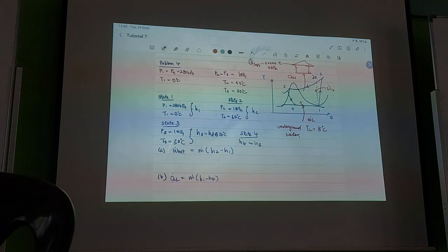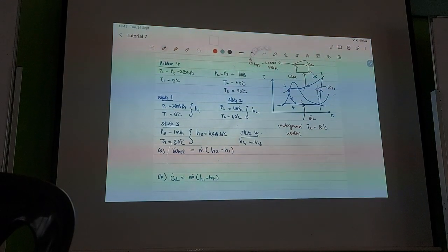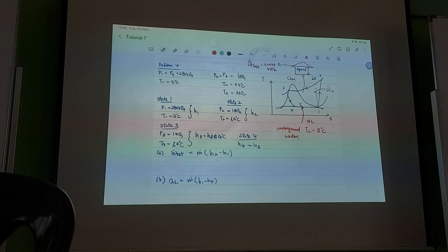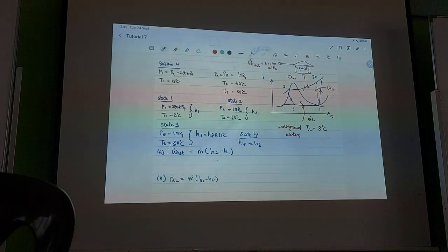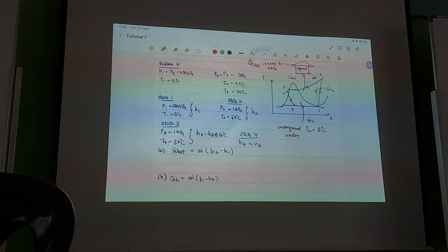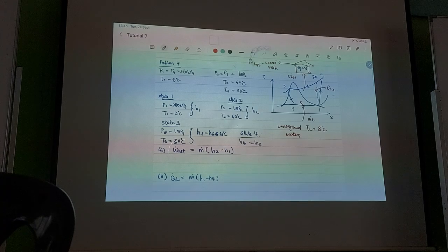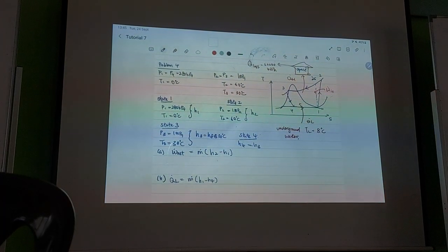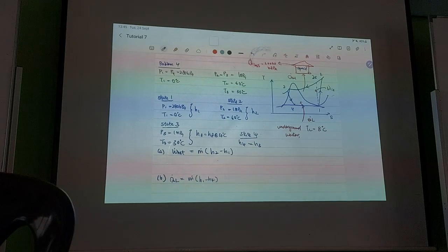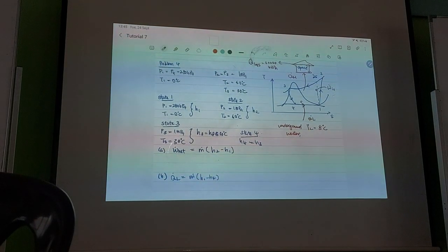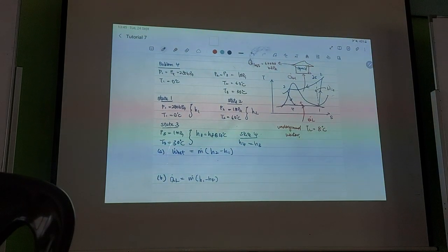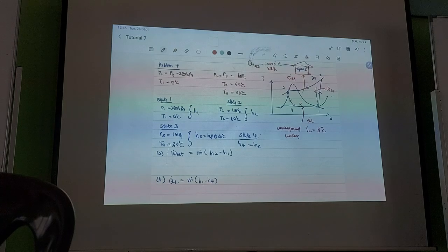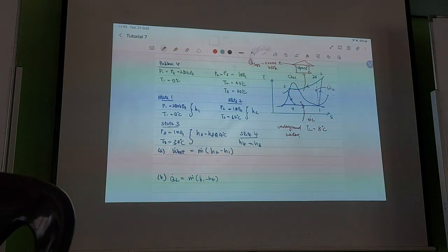Yeah, in order for you to maintain this space at a fixed temperature, Q gain must be equal to Q loss. Because if QH is higher than Q loss, then the house will just keep getting hotter and hotter. If the other way around, then you will keep getting cooler, then your heat pump is useless.